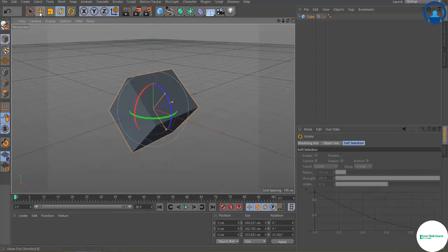The same with the transform. See, I can click over here and you can see it's reset to the global coordinate system. When this gizmo moves, rotates or scales according to your object, we call that the object's coordinate system. But when it gets reset to the viewport, we call that the global coordinate system. Shortcut to activate this is W.